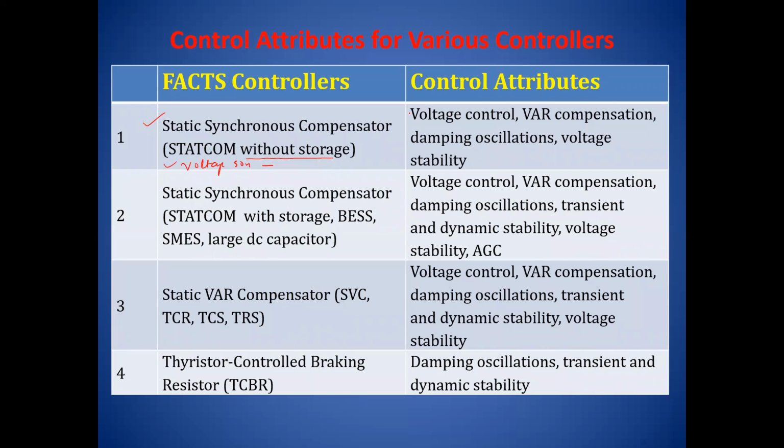It is voltage control. It will do the voltage control because as it is connected in parallel, it injects or consumes reactive power. If it is a capacitor, it is going to deliver reactive power kVAR, and if it is an inductor, it is going to consume the surplus reactive power in the transmission line, because of the length and capacitance of the transmission line, to maintain a constant voltage. So this is one objective which we obtain. It is a controlled VAR compensation.